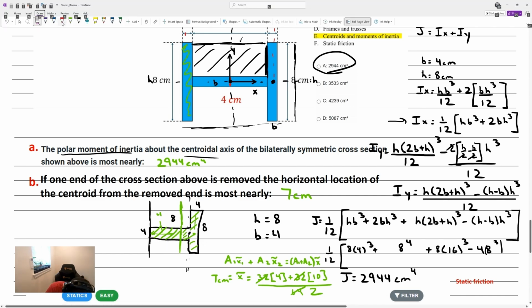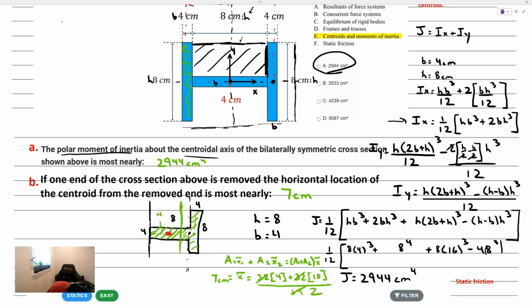In this configuration here, the moment produced by this 7 by 4 area and the moment produced in the other direction by this small area and this large area, they're exactly equal. And because they're equal, if you place, let's say, this shape on a wire at that point, it would balance, right? Left and right, and you would expect it to stay in perfect balance there. In summary here, if we place an axis at the centroid, intersecting that centroid point, the moments of areas left and right of that axis will be in perfect balance, and we'd expect that object to stay in equilibrium.